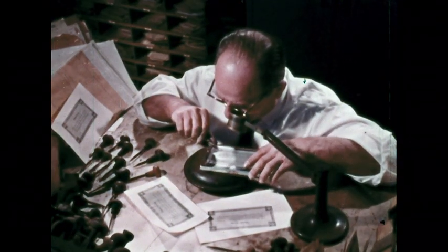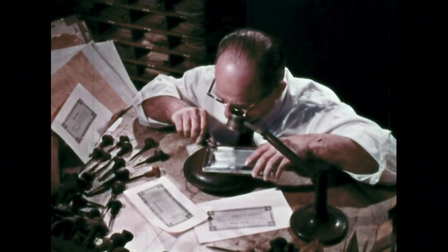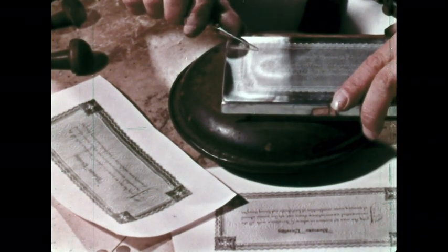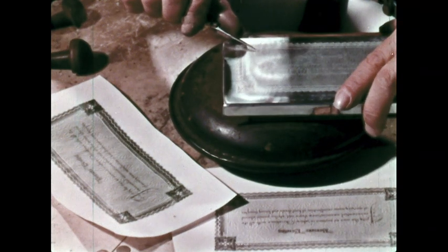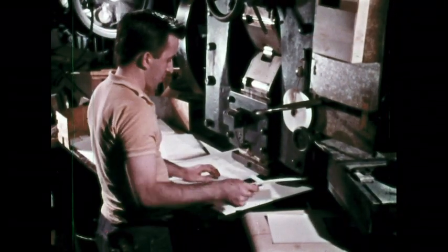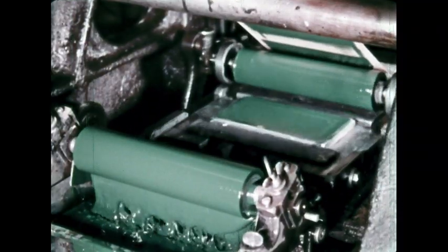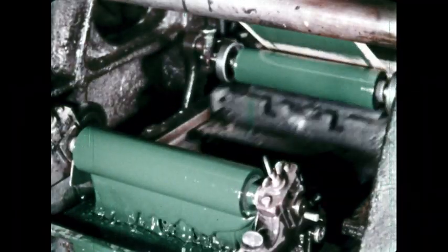Steel die stamping and copper plate engraving are applications of gravure printing. In both methods, the printing image is cut into the surface of the plate, and both use all three types of presses: the platen, the flatbed, and the rotary. They're generally used to print fine stationery or other work requiring fine details, such as stock certificates and money.